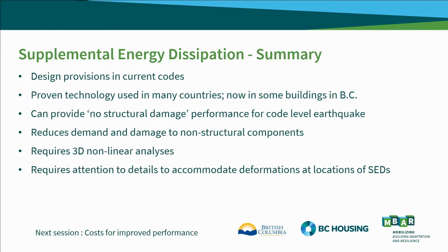Again, that reduced demand and damage to the non-structural components in a building. It does require more analyses at the beginning in the engineering phase. And it does require special attention to detail to accommodate the deformations at the location of these devices, because deformation is what drives the energy dissipation, so it needs to be very carefully considered.